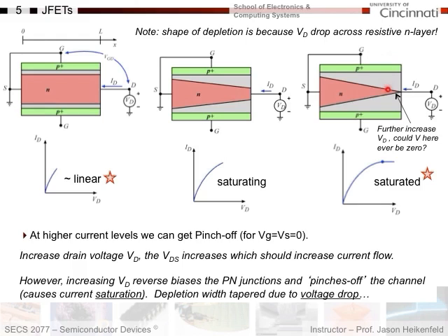So then you could say, okay, it opens back up, but then the voltage starts to appear in the channel again, and it shuts itself off. If it's shut off, then that 0 volts gets back in here because there's no current and no voltage drop, and then it opens back up again. And so you'd have this balance of it trying to shut itself off, but it never can, because if it ever shut itself fully off, it would find itself in the non-shut off case because you would have 0 volts here and no reverse bias. And if you looked at this even more closely, you would find that even if you have a barrier here, it could be so small at this very end that you could get tunneling of carriers through it.